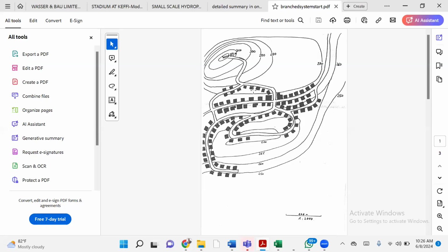And we said that the primary pipes sometimes can be like 1 meter, 1.5 meter, 900. The secondary pipes can come down to 600, 300, 450. Then the tertiary pipes can come down to 75, 100 mm, 150, and so on and so forth. So you can see the cascade. As the water is going downstream, the pipes are reducing in size.